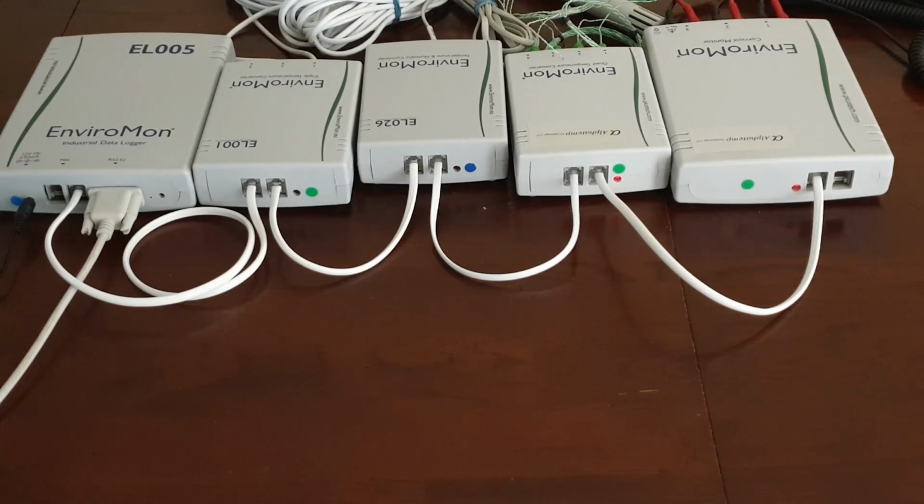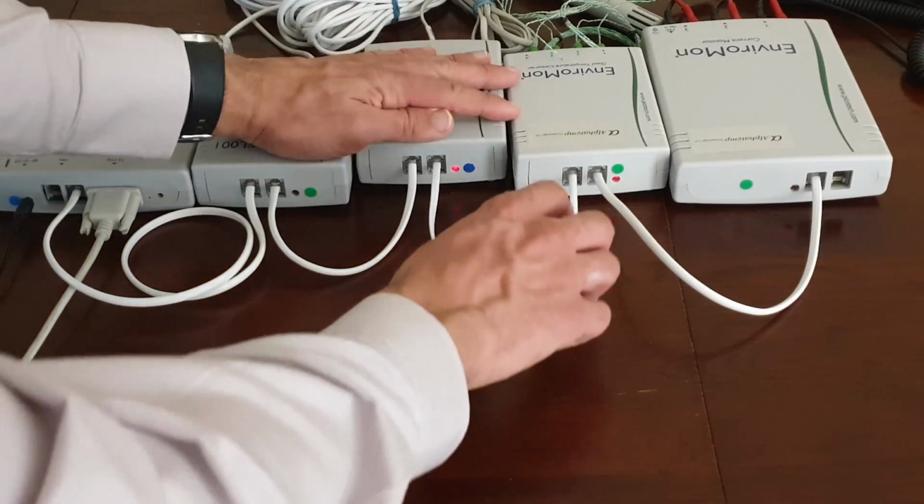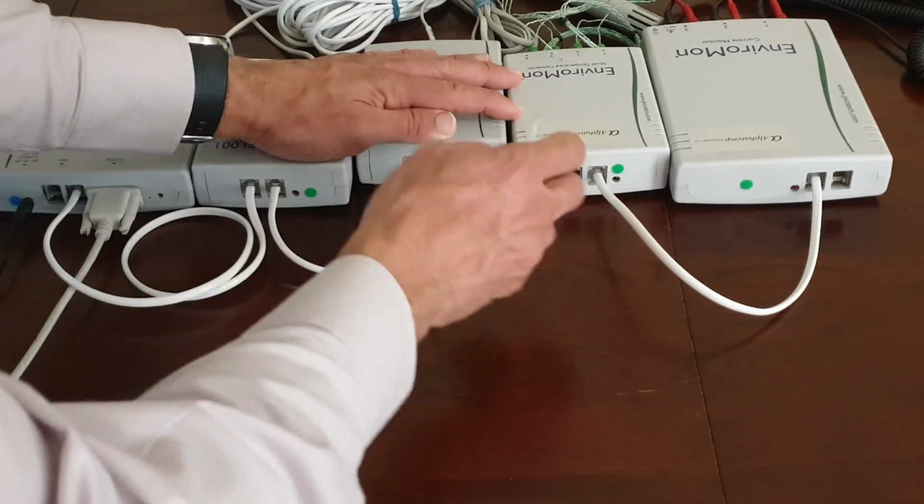So if we look at the LED on the third and fourth converters, they seem to be exhibiting different behaviors. The LED on the third converter seems to be permanently on, whilst the LED on the fourth converter seems to be flashing very quickly. Now this would indicate that there's a problem with the converter cable from the second converter to the third converter and possibly between the third converter to the fourth converter. So we're going to replace the cable from the second converter to the third converter and see if that fixes the problem.